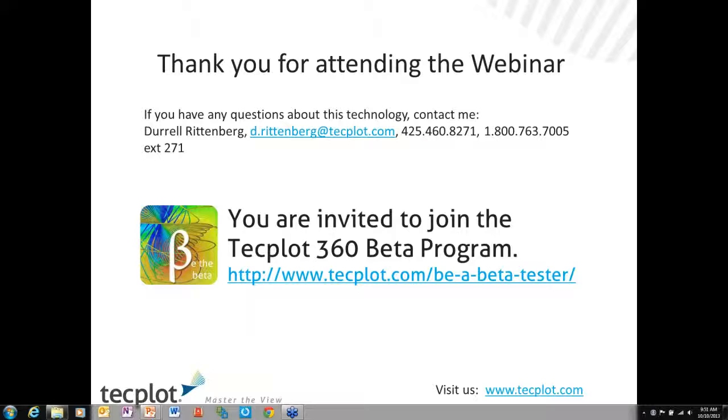Okay, so are you loading and computing the isosurface? Yes, we are, Stuart. We're actually using the calculation of the isosurface and then using that to go into the subzones and pull out the right information. So the process is you go into the tree file, you query it, you say, which subzones do I need?